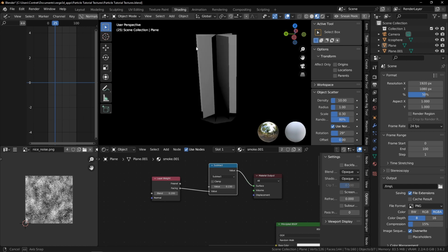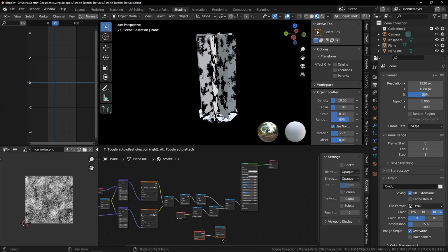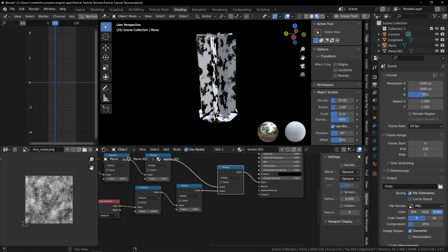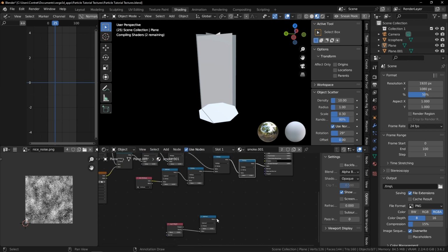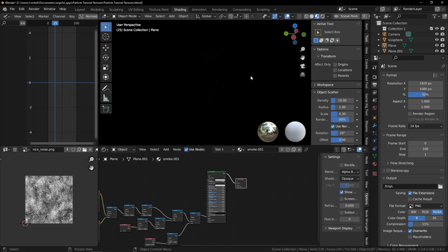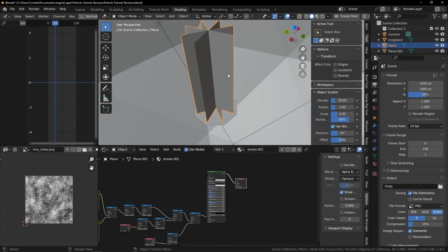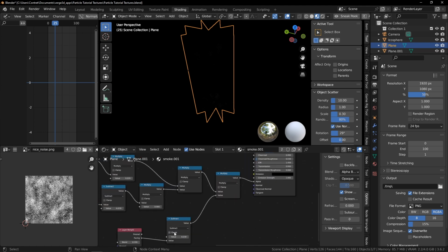Something like that. And when we are happy with the result of this mask, let's move it down, change the shader back to alpha blend, and multiply our alpha by our new mask. Alright, if we don't see anything, we need to play a little bit with the mask and with the visibility of the main alpha.